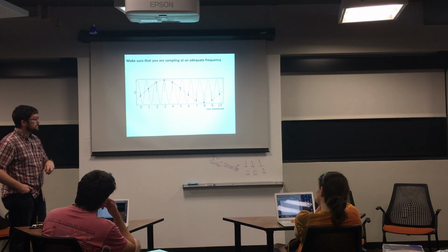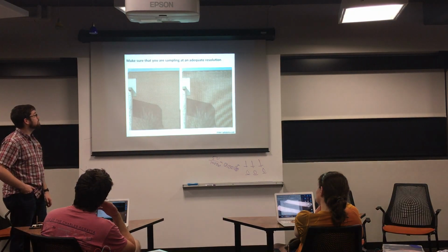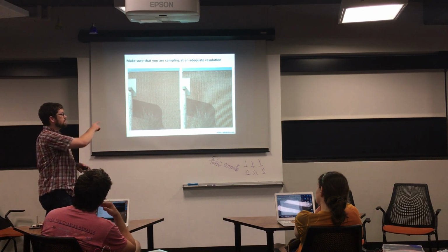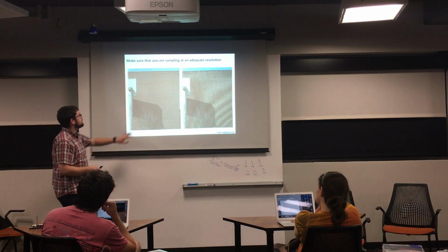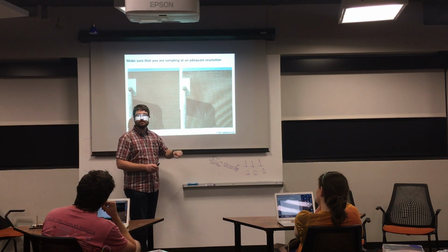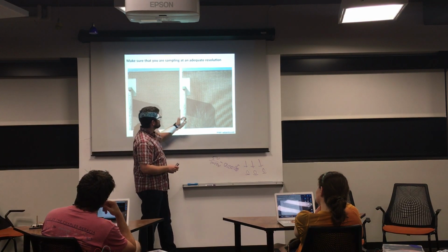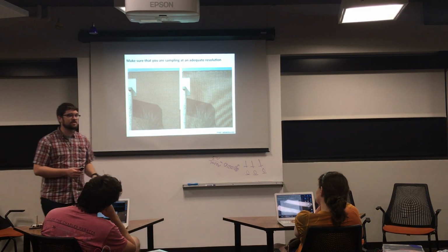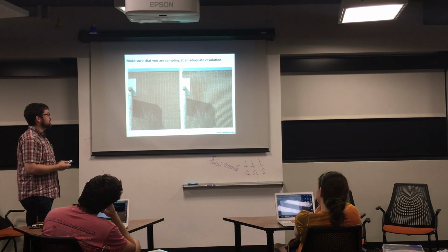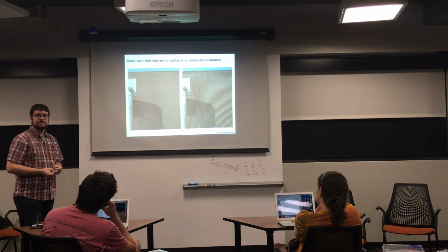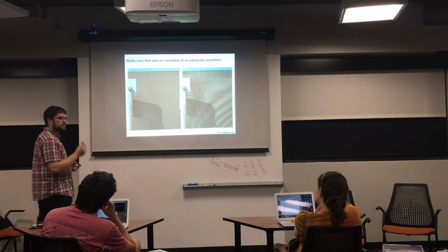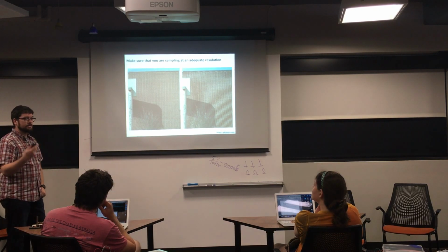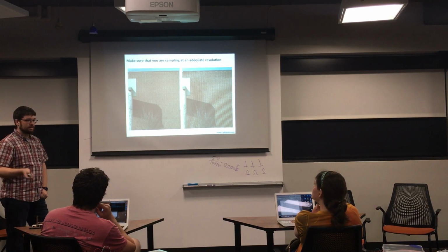So there's a criterion for how fast that you should sample at the minimum. Oh yeah, this is another fun one. It's not just 1D time series. It can happen in images too. So this is an image of a brick wall, and then if you continually spatially downsample it, eventually when the resolution goes below the pattern in these bricks, you get these artifacts that get introduced into the images. So if you're taking pictures on, especially older cell phones, would do this quite a bit. I don't think anything on an iPhone, unless you're looking at something really fine. But so it can happen in images too, pretty much any data, audio, time series of stress, whatever.